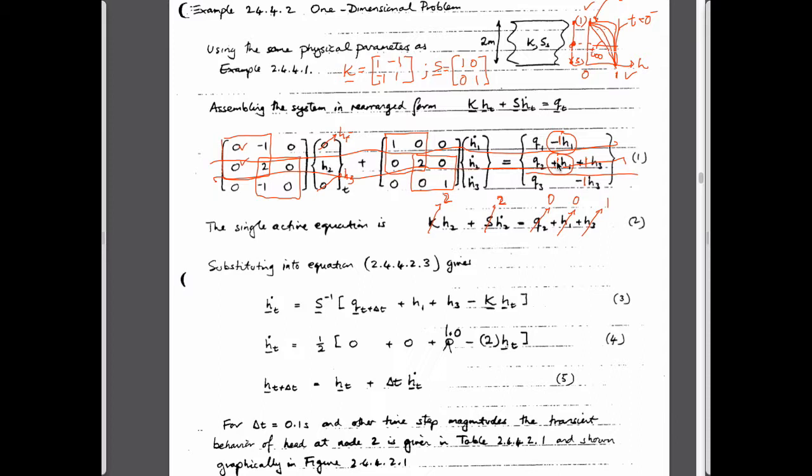This is an incompressible system except for the storage, and so in steady state there still has to be no mass accumulation, but there can be exchange between stuff coming out of storage in one location and going into storage in the other location because the heads will change. And so all of the compressibility, if you like, of the system is accounted for in that capacitance term. Okay, so we can always assume that.